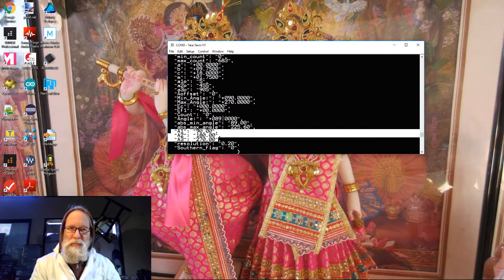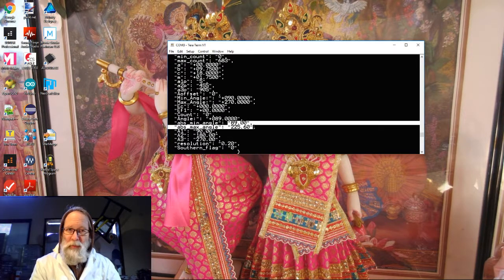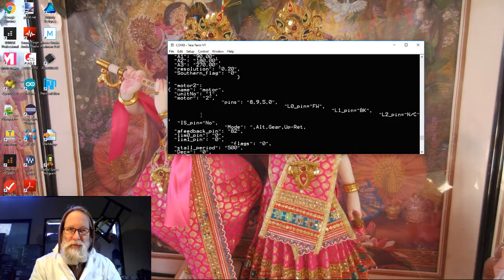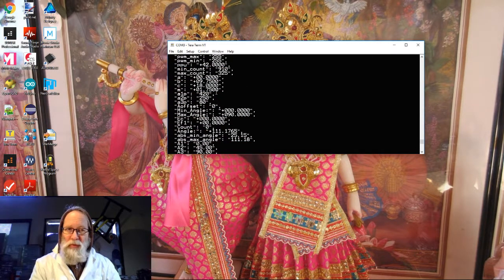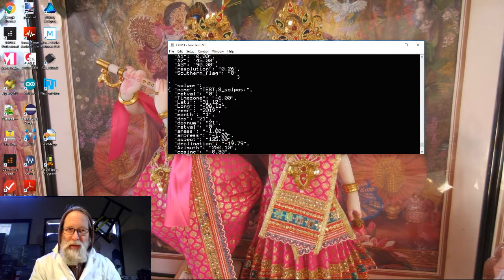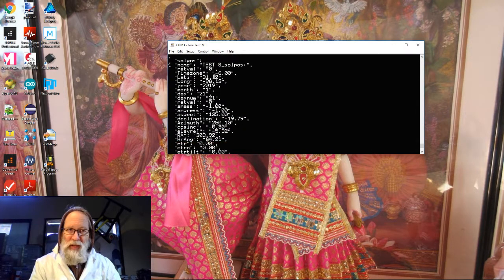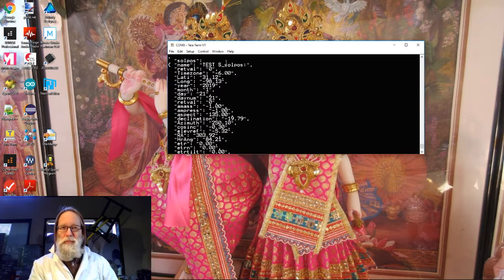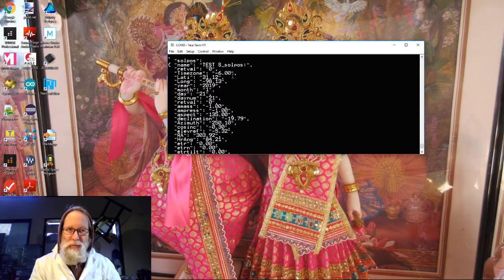Here's the absolute minimum and maximum angles that are calculated by the system based on the pulse count, etc. So we've got the same information for M2 here, the elevation axis. And then lastly we've got the solar tracking position calculation information. Once again, you can see where air pressure factors in.